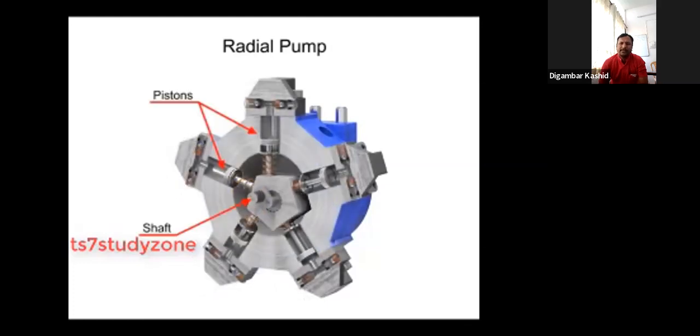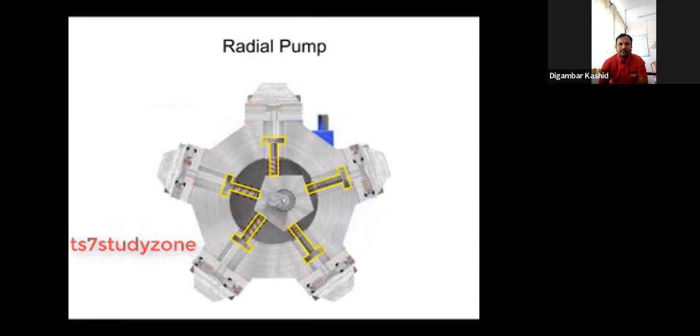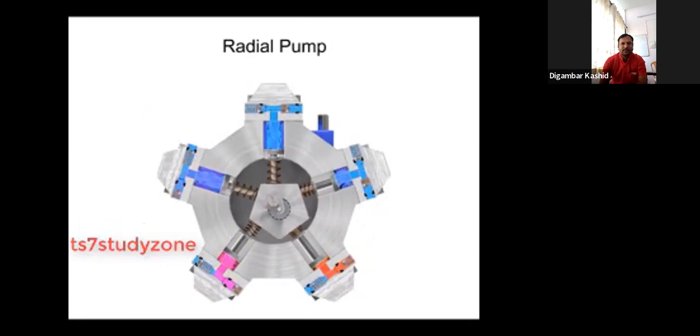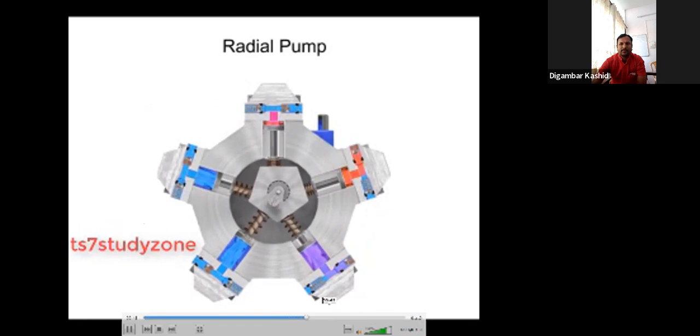Air motor, okay, same is there. See, the pistons are arranged like wheel spokes around a cylinder block with an eccentric central cam mounted on a drive shaft. As the shaft rotates, the cam moves towards the pistons, forcing them down into the cylinder block and discharging the fluid. As the cam moves away, springs help ensure that fluid only enters the inlet ports at low speeds.